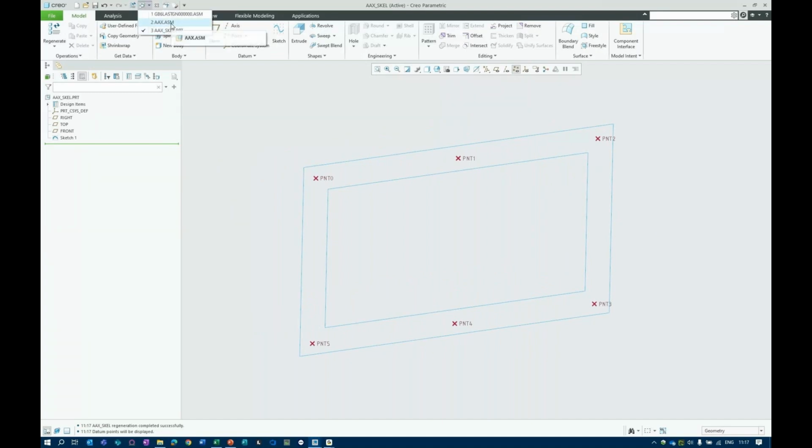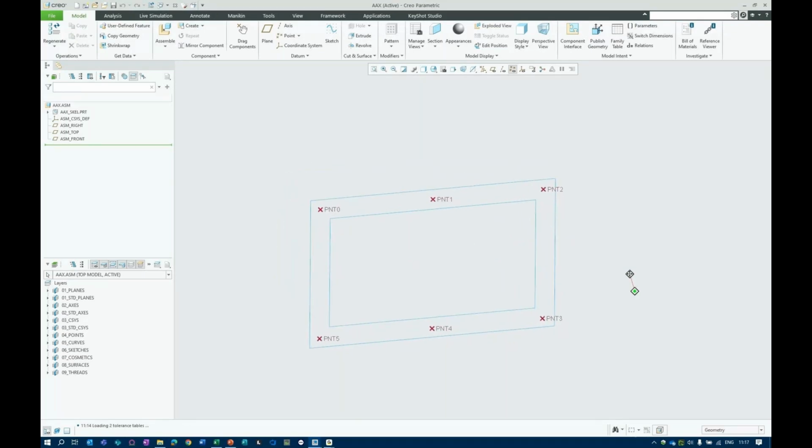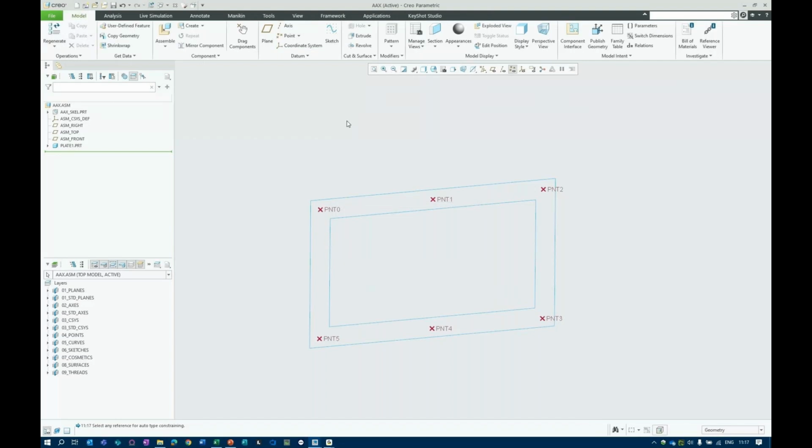Now, if we go into our assembly, you'll see the same coming up, of course, and now we want to create our parts. So again, in context, I will create a new part. Let's call this plate 1. Okay, that's a new part. Because I have nothing in there to place it against already, it's easiest that you just position it at default. You can work with the different positions, but in our copy geometry that we create later, we have to teach it.